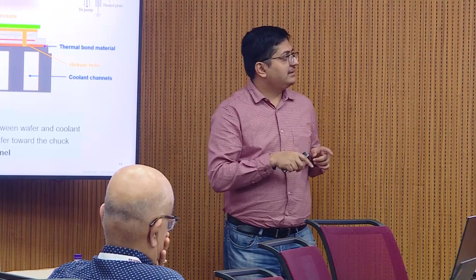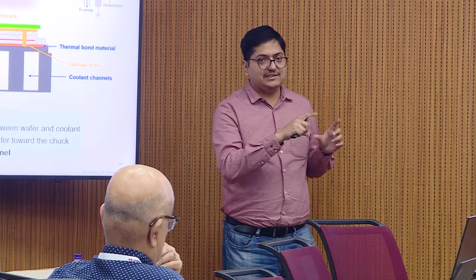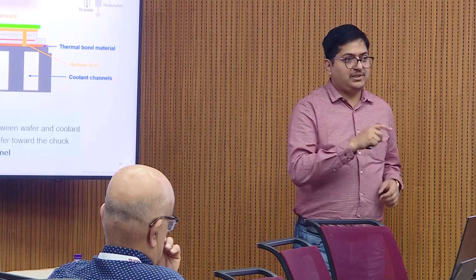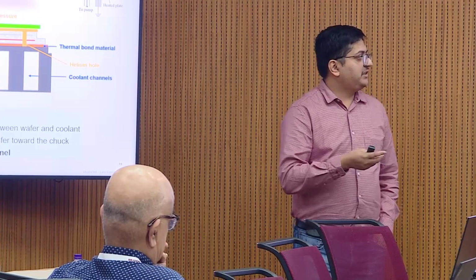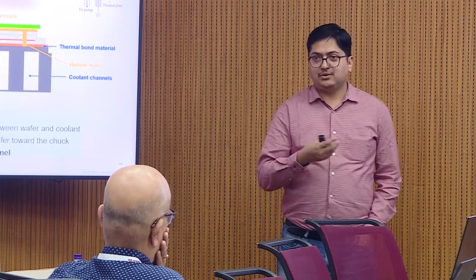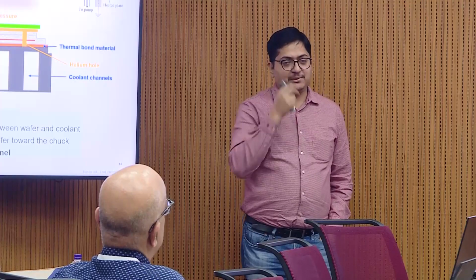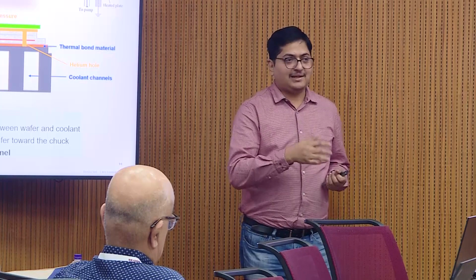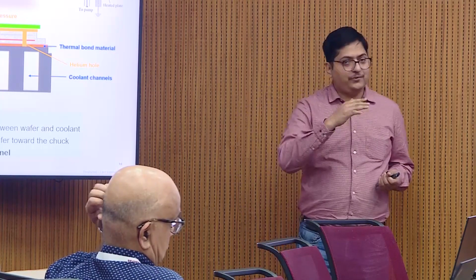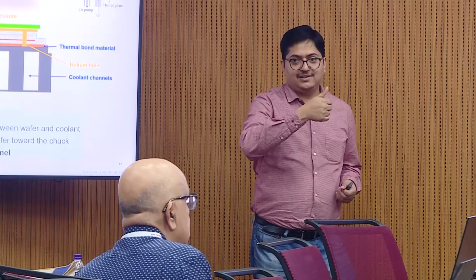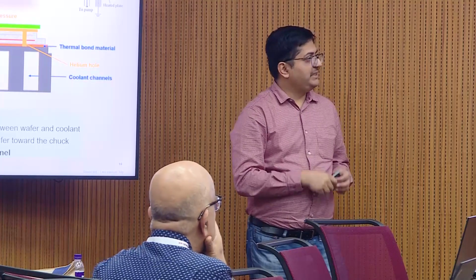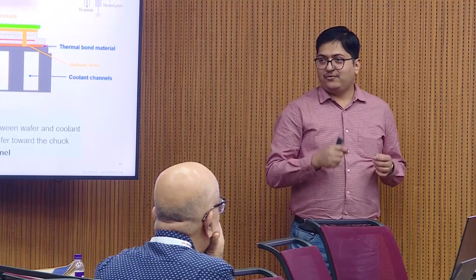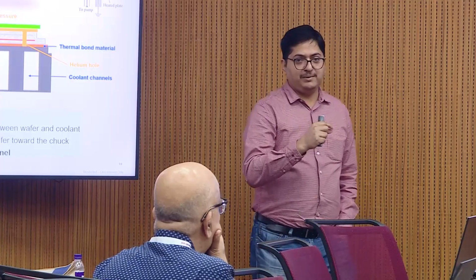Now this whole system works in a vacuum chamber, and if we supply, say, 40 to 50 torr of helium pressure, where 1 atmosphere is almost 760 torr, you can do a simple calculation and find that this wafer will experience almost 50 to 60 kgs of upward force, which tries to fly up the wafer. And we need something to hold this back. And the wafer is a very thin element, right? It is less than 1 millimeter in thickness.